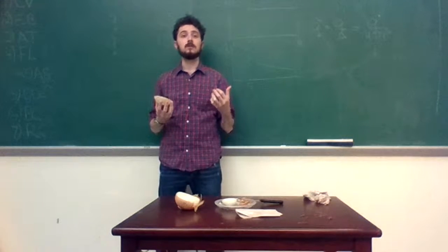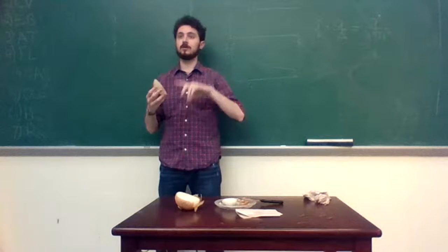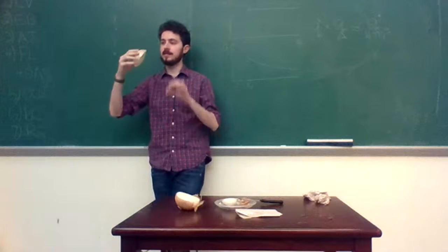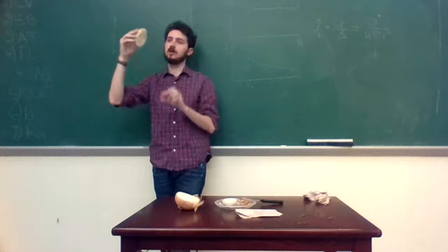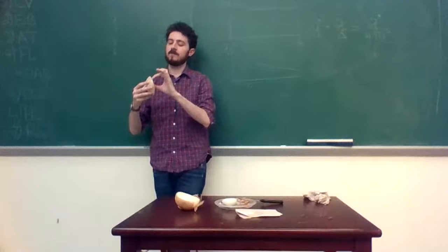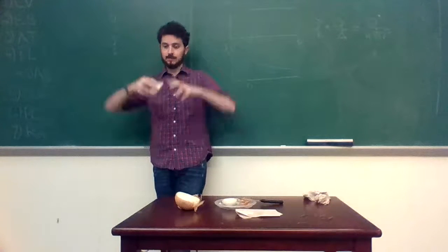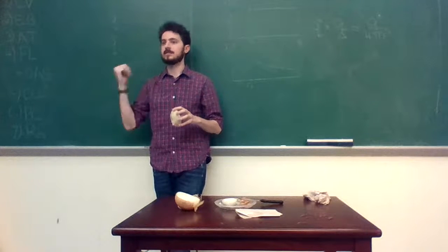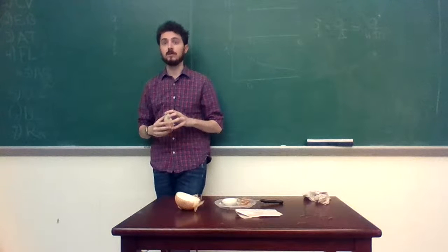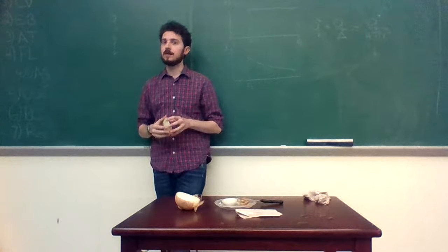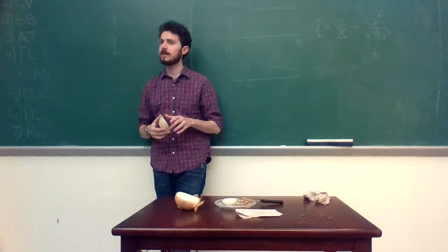One thing that will change is that the spherical description becomes more important at that point. When you're dealing with a really thin walled onion like this, it is not that different, it would be very, very similar quantitatively. When you've got very different R1 and R2, and you've got a lot of spherical mass, then it becomes a different problem, and doing this full-blooded spherical description matters more. I think we did a little numerical example of this in office hours on Friday or on Monday. Is anybody here for that? A few of you were.